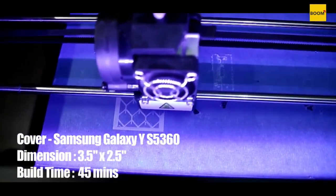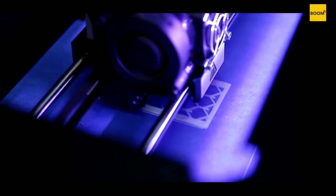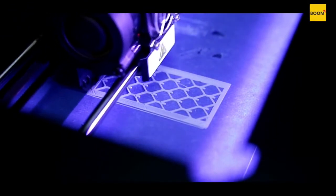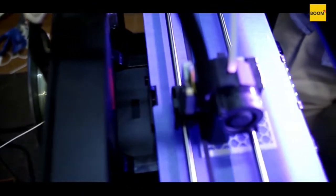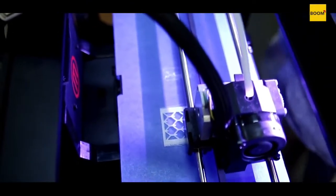While printing, you have to be careful that the geometry of your object is clean and that your print is not shifting during the print. You have to keep it anchored and firmly stuck to the build plate. In addition, you have to ensure that any cantilevers or projections from the print are handled correctly by the printer.